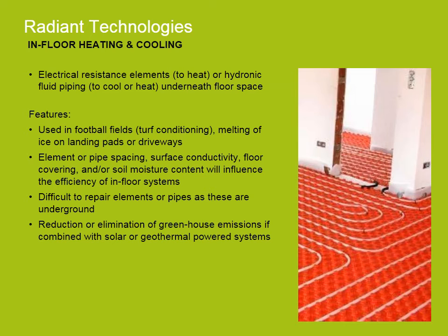This system works in much the same way as a chilled beam, however it has two key differences. Firstly, this system can be used either to heat or cool, depending on the setup or use of the refrigeration cycle. And secondly, in-floor systems make use of the thermal properties of the flooring materials to either store or dissipate heat where appropriate. The element or piping spacing, the surface conductivity, the type of floor covering, and the soil moisture content all take effect on the efficiency of an in-floor system.